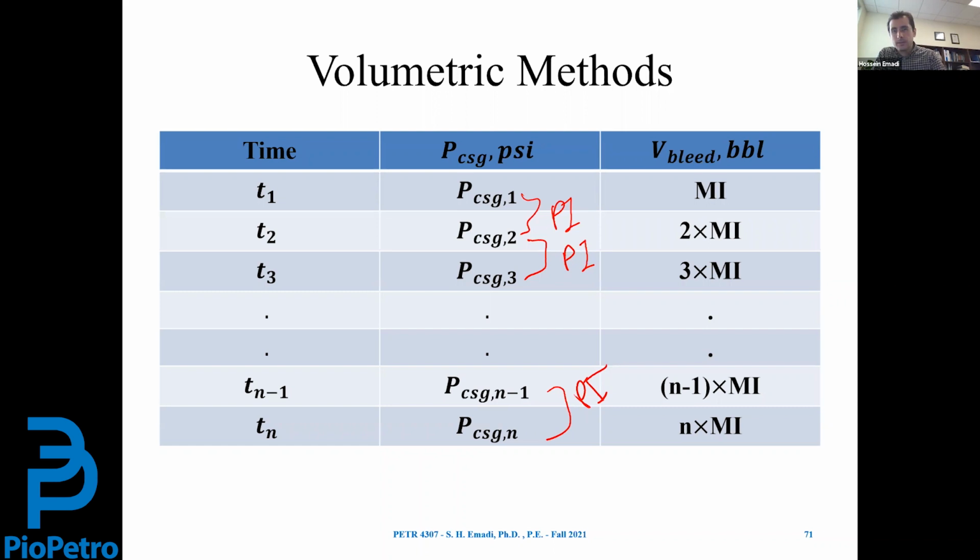So basically, we're reducing the ECD to minimize or stop lost circulation, or we can pump LCM materials to reduce or cure the loss issue, or we can go and set a cement plug, basically to cure or take care of the loss zone. These are probably three normal procedures that can be done during the operation when we're dealing with a lost circulation zone.